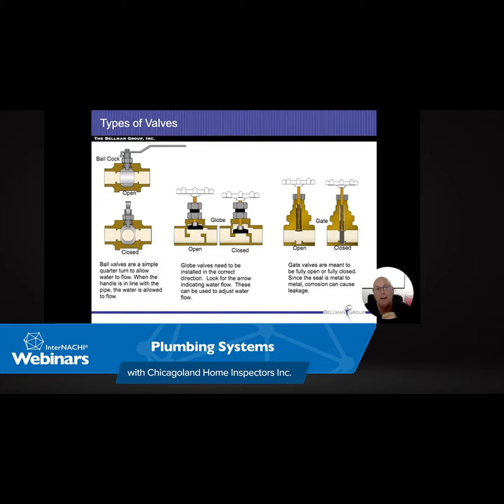So if you put the oil in there and the smells come back, chances are it needs to be rodded, jetted, whatever. Or if it's pieces that are replaceable, replace them. Something to do if you're going to leave it vacant for a long time. If it gets used a lot, it really doesn't come into play. S-traps, we kind of talked about that before. They create that siphon or that momentum, and if we get all the water out of there, then sewer gases are going to come back in here.